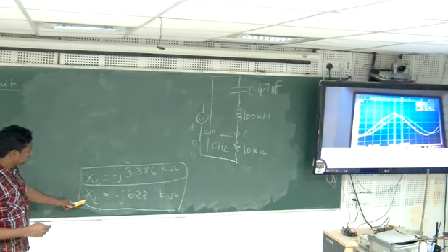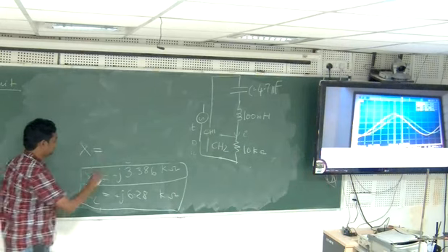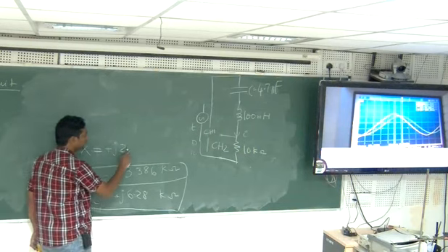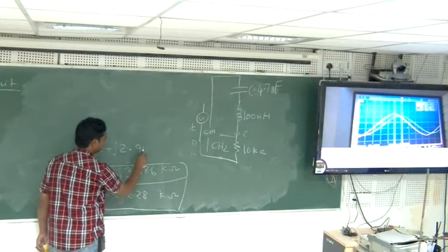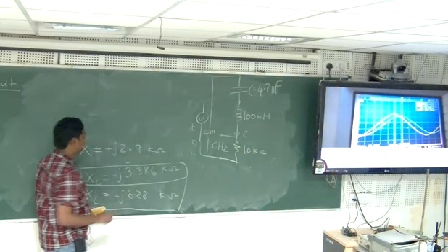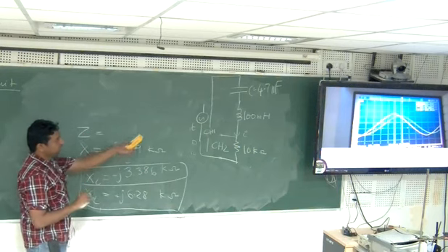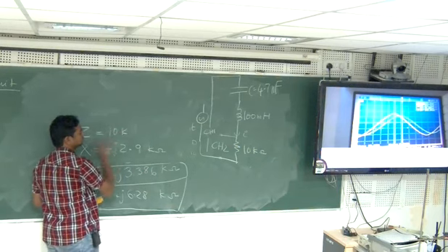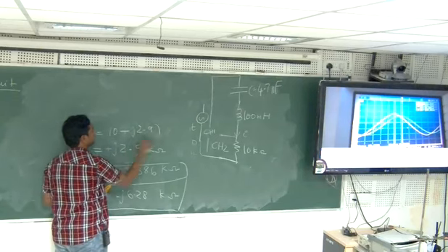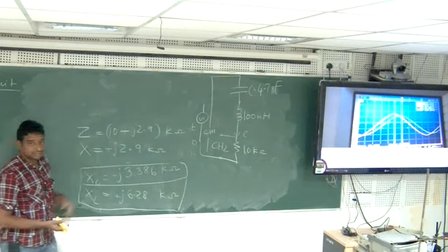Okay. Now, what is the net reactance? X net reactance. It is plus J. How much is that? 2.906. So I'll call it 2.9 kilo ohms. This is net reactance. So what is the net impedance? So my resistance is still same, 10 kilo ohms, plus J 2.9 kilo ohms. Okay, are you following? This is my net impedance.